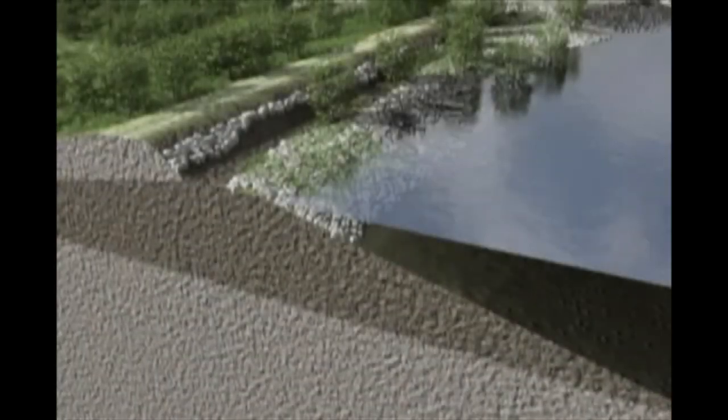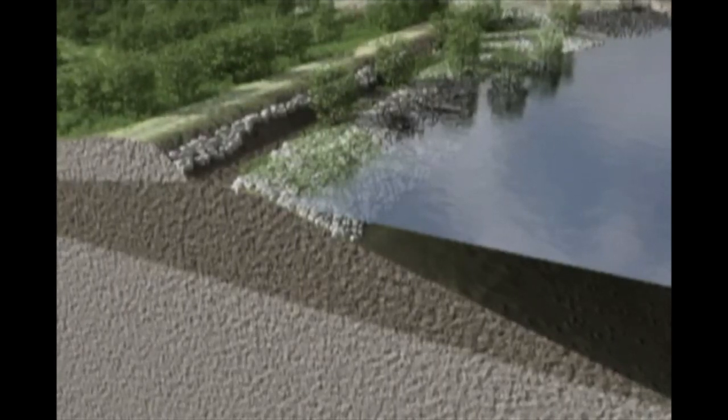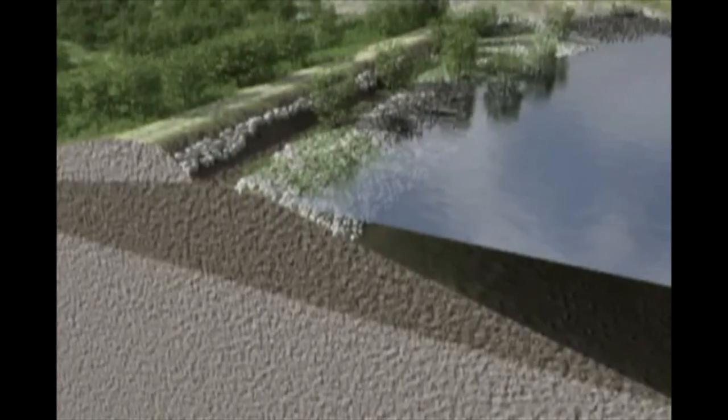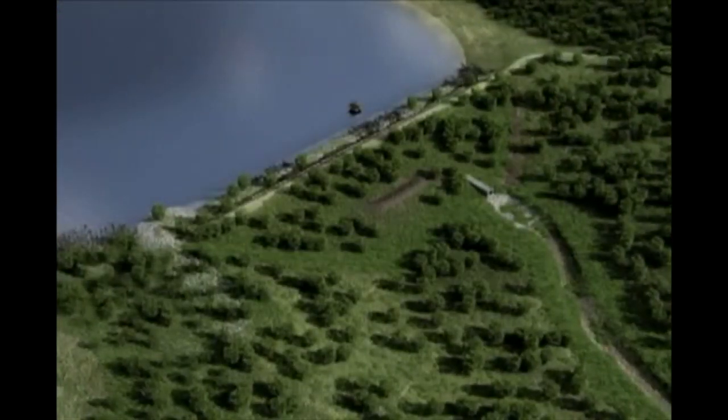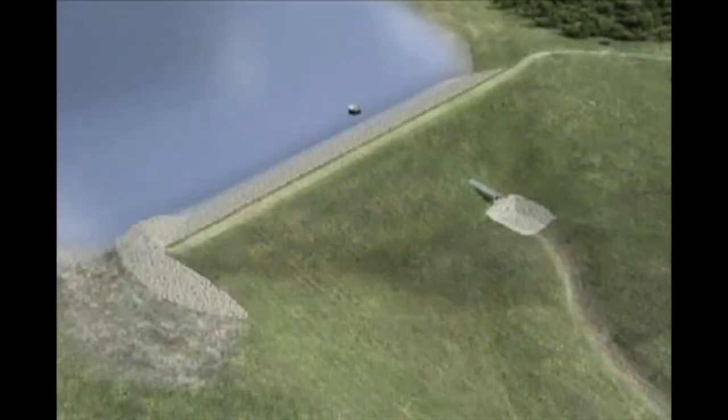Debris can block the spillway inlet, leading to increased pool levels and possible embankment overtopping. Riprap should be carefully inspected and replaced as needed. Wave action can damage the slope protection, exposing underlying embankment soil to rapid erosion. Debris left to collect on the upstream slope can damage the slope protection and hide problems. Keeping a dam in good condition is important and will prevent problems which could lead to failure.